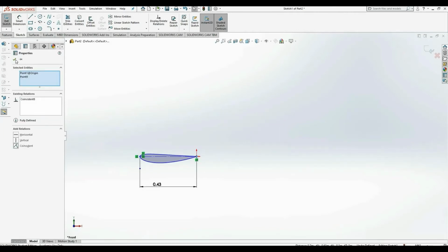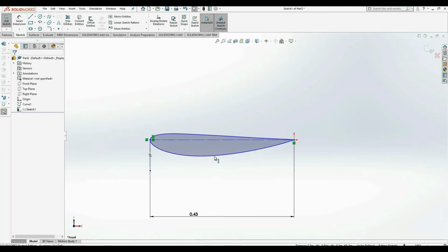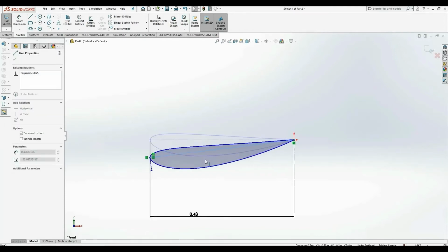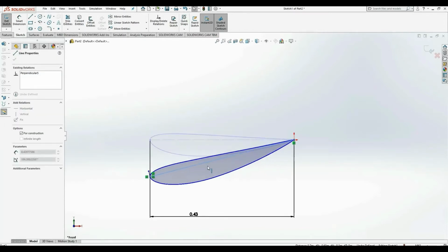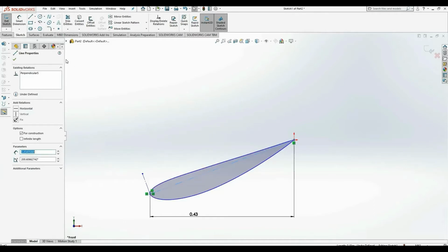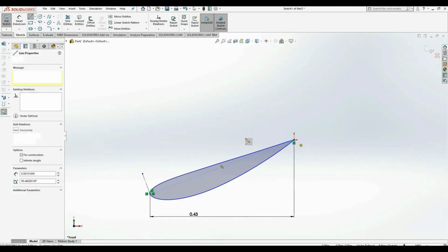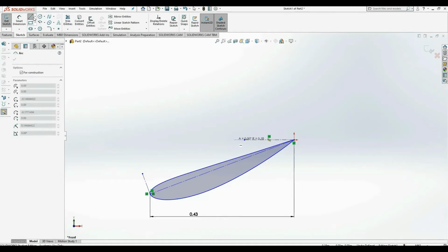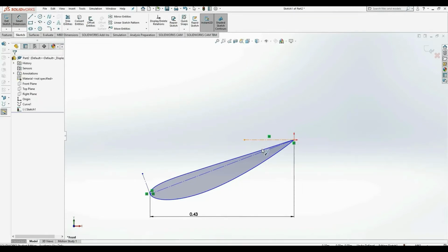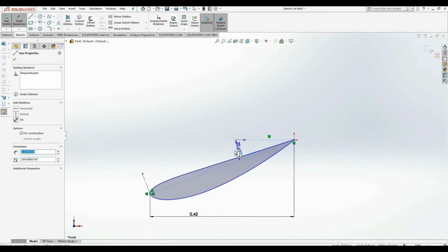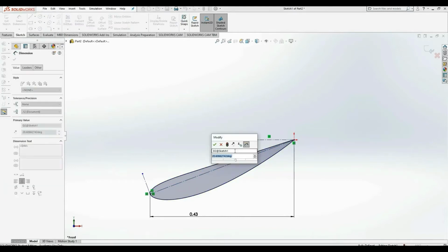So angle of attack, we want to make sure that we can create a firm and fixed point, which we're going to use as the trailing edge because that's a single point, and all I've done is I've attached that single trailing edge point to the initial origin. And now I'm just going to add a construction line again, in which I can dimension our chord line versus the construction line, and that can give us the aerofoil's angle of attack.